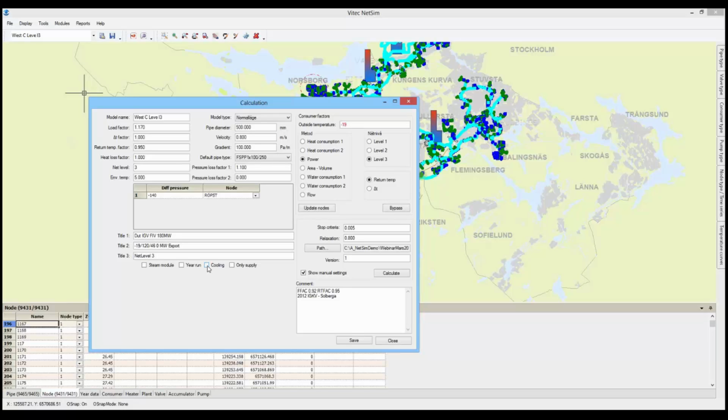Then maybe you can reduce the size, or maybe you should hold the size up. That's a lot of money you can save if you use, for instance, DN 250 instead of DN 350, or 100, for instance. Maybe you can use a twin insulated pipe instead of single pipes. Okay, great. Do you have any more cases that you have found?